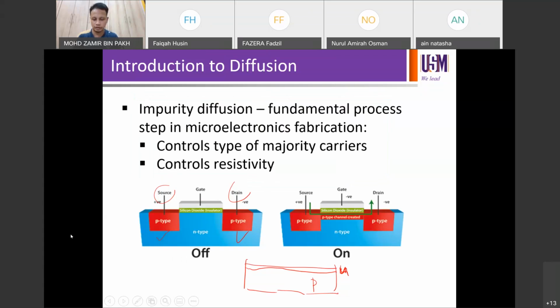You can go back to the previous page. For example, if you have something like this, the p-type is typically around 10^16, the n-type is typically around 10^19, but within the n-type up there, you also have some heavily doped region in isolation. So you may have the blanket dope to be 1E19, for example, but this one may go up to 7E19, just in an isolated region.